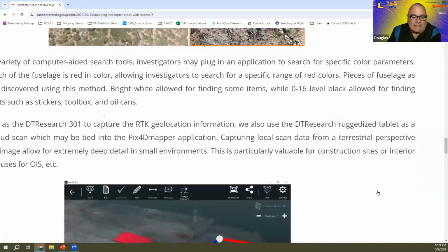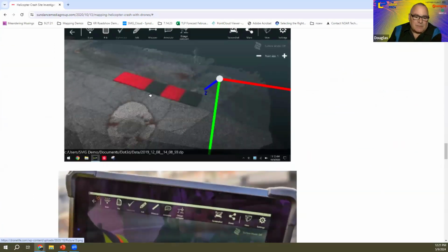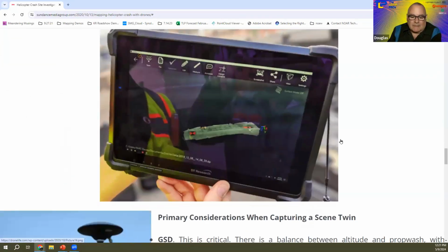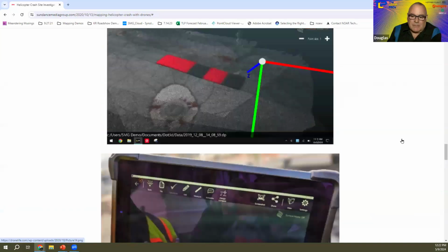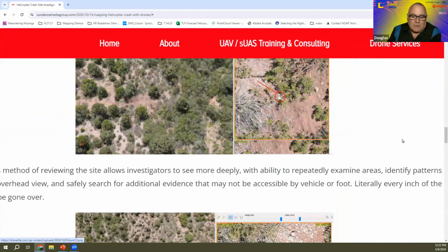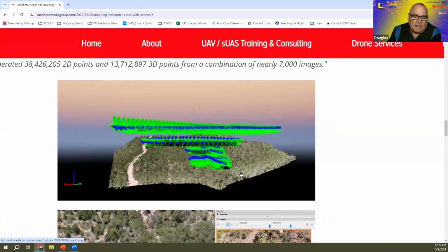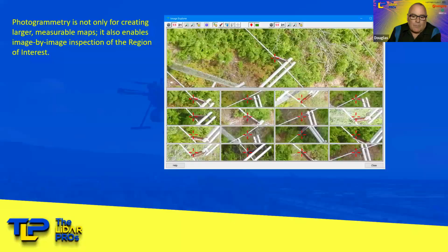In this particular session or indication here, you can see where we laid out a sky ruler for scale, and we've got some ground control points that you can see here in the image scene. So this particular project was really large. We had a lot of data that we had to put together, but we were able to take all this data over 77 acres and 7,000 images and tie them together using the ground control points that we just spoke about.